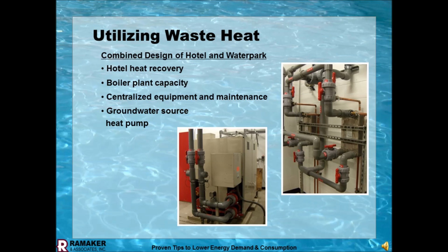Where it works best in the original design is if you have a centralized boiler plant, a centralized boiler that's serving the hotel, convention center, and pools. Maybe you have multiple boilers, so if one goes down, you're not totally shut down. You use heat exchangers as opposed to individual gas-fired pool heaters, to heat the pool water, and you can tie that in with the air handling unit.